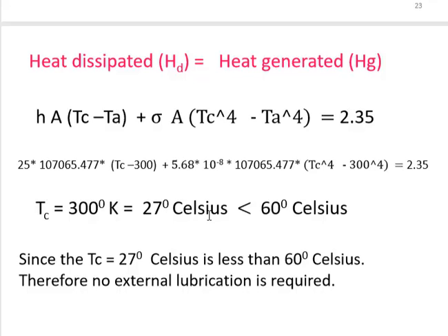The thumb rule is that if the temperature of the casing does not exceed 60 degrees Celsius, then external lubrication is not required. Hence we don't have to design any lubrication system for this particular clutch box.